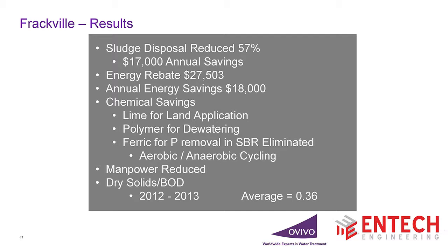And these digesters had their own blower. So that wasn't a guesstimate. That was measured by PP&L, independent third party, if you will. So again, those energy savings are real and verified by another outfit. Chemical savings, well, if you cut the sludge by 57%, you cut the bags of lime by 57%. The operators loved me for that one. We cut polymer into dewatering.